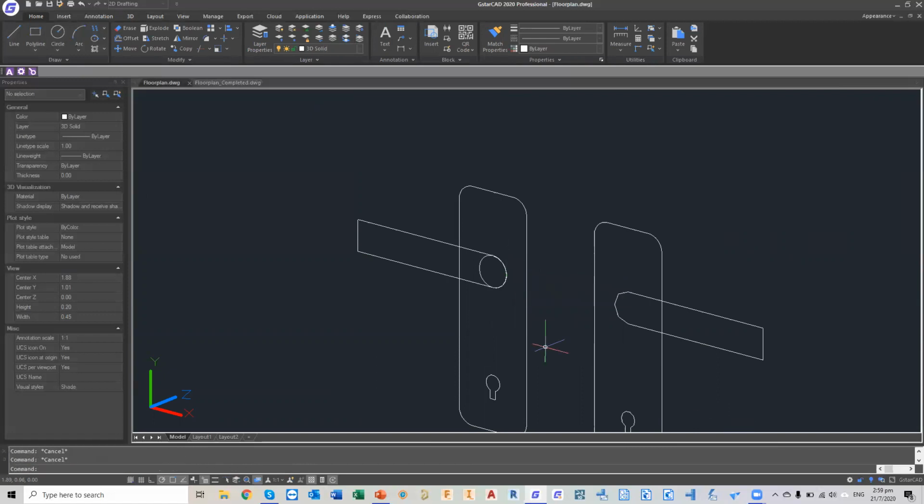Okay, that's the shape of my handle. And then I need to tell what is the bending angle of the handle that I want. In fact, the handle I'll be creating using the sweep command. All right, so I'll be using the sweep command to do that. So in order to do that, we need to know where is the sweeping direction.